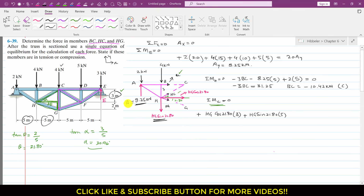Similarly, this Ay reaction is producing the clockwise moment about point C, so I have to write minus 8.25, and the moment arm of this Ay from point C is 5 plus 5, this is 5 meters and this is 5 meters, so we have to multiply it with 10. Similarly, this is producing the counterclockwise moment about point C, so I will write plus 2, and the perpendicular distance of this force from point C is 10, so I multiply it with 10. And similarly, this 4 Newton force is producing the counterclockwise moment about point C, so I have to write plus 4 and multiply by 5.